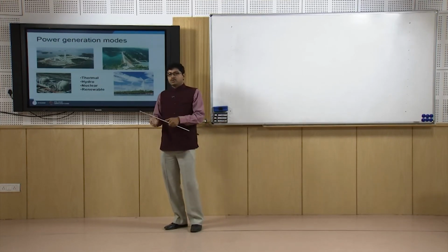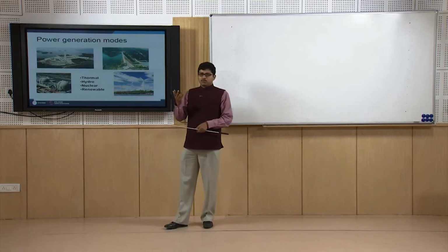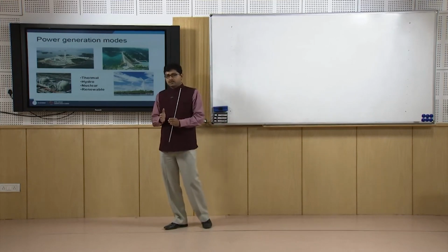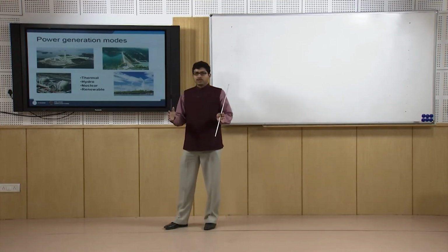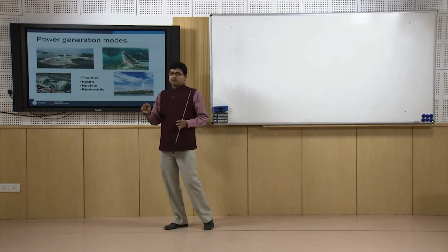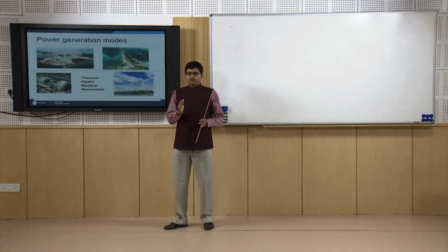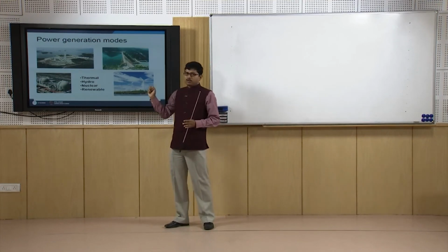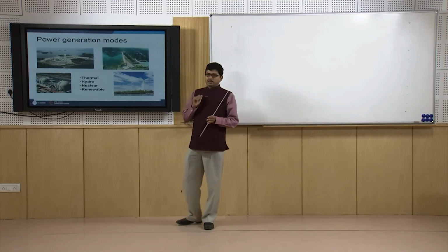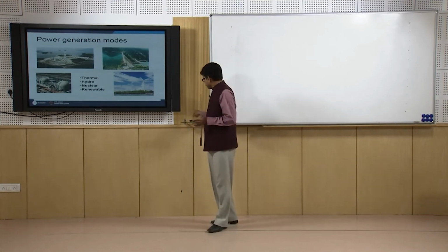Sometimes the electricity wires are put underground or they can be overground. Whatever it is, the basic focus is that we need a dedicated space for electrical installation along the road and at the substation area. If you are going to develop a large area of land in a bigger housing project or township project, you have to keep some area, ranging from 2 to 5%, for power generation, electrical distribution, the substation and the distribution wires along the roads.